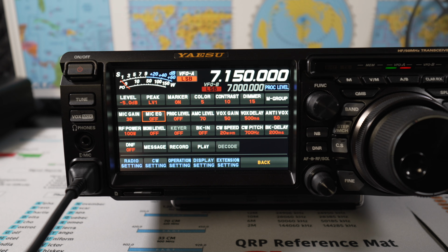The first thing that confuses new hams is that they set the radio to 100 watts, but they don't see 100 watts when they transmit. Now why does this happen? Single sideband is not like AM. It doesn't output a carrier along with the modulation of your voice. It just outputs the modulation of your voice. So if you key the mic in single sideband and you don't speak, you'll get zero output like we saw.